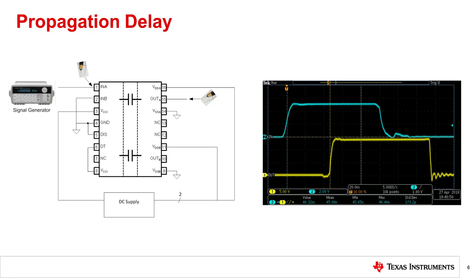For maximum accuracy, the approximate rising and falling thresholds should be located with an adjustable voltage source beforehand by increasing and decreasing the input voltage in small increments until transition is observed. Keep in mind that these thresholds will change with changes to supply voltage and temperature. Adequate bypassing capacitors must be present to ensure consistent internal supply voltage.